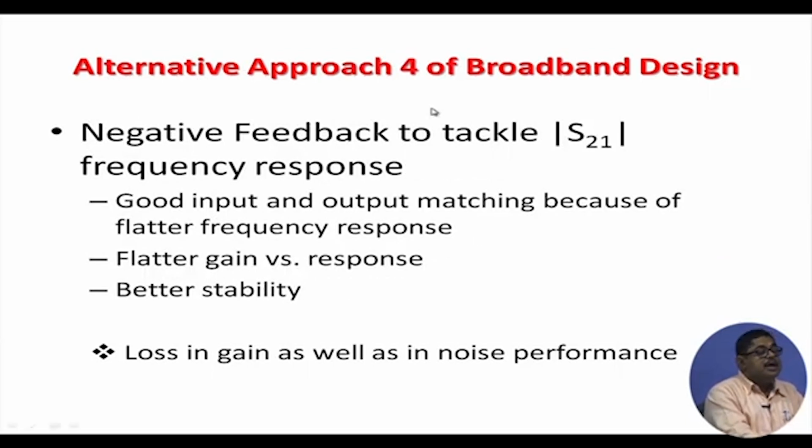Fourth alternative, here negative feedback you can use. Any negative feedback will make your input and output matching better, because any negative feedback flattens the frequency response. So, S21's frequency response with feedback will be a bit flattened.